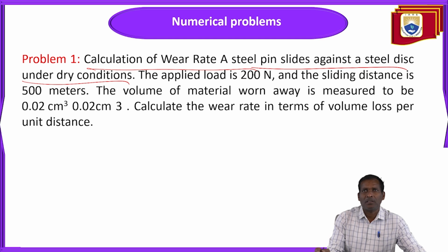Pin on disc testing can be based on dry conditions or wet conditions, so the wear rate is calculated under dry condition first and under wet condition second. The pin slides on the disc. The material for which wear is to be calculated acts as the pin, and the disc is made up of another material.